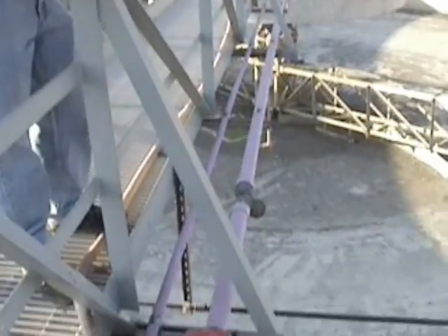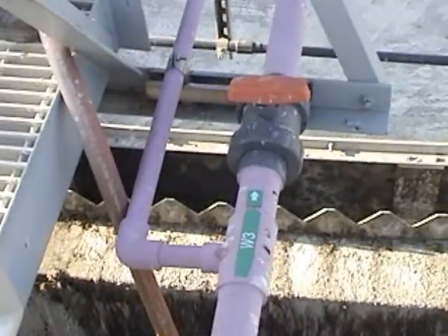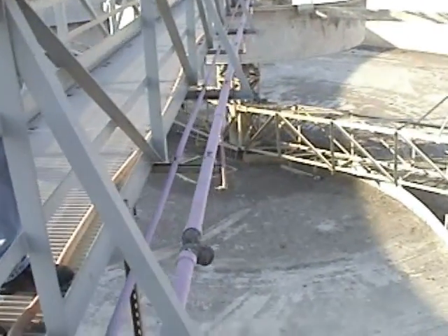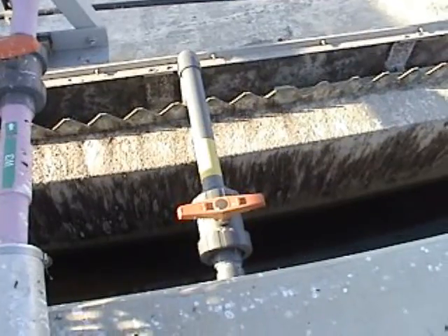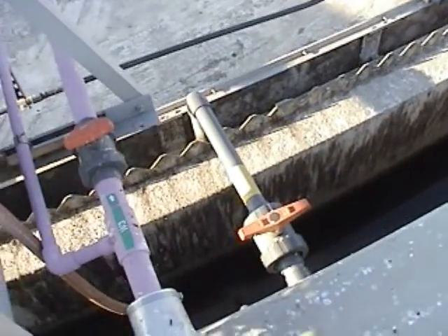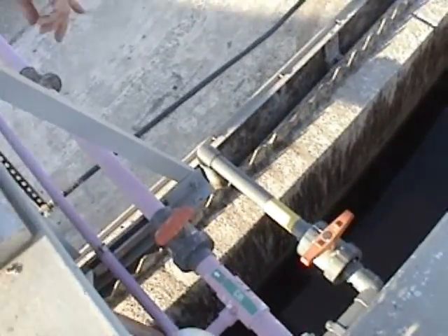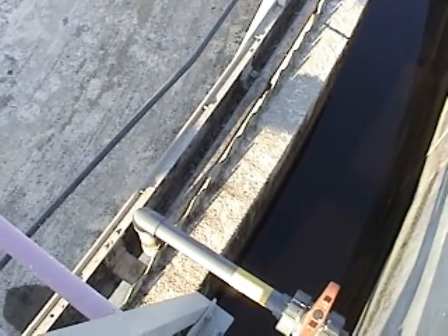There's two pipelines here. One, the purple line, is utility water. It provides water to the foam sprayers to break up any foam that's on the surface of the secondary clarifier. Then the other pipeline with the orange handle on it and the yellow color coding, that's bleach solution. If you wanted to control algae growth on the weirs of the secondary clarifier, you can feed bleach directly in through that line right there to the perimeter of the secondary clarifier, and the bleach will flow over here and kill off all the algae. So you can see that. And the bleach flows out of those little 90s that are on that pipe.